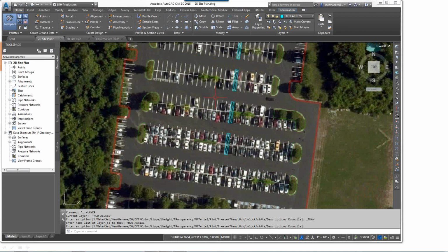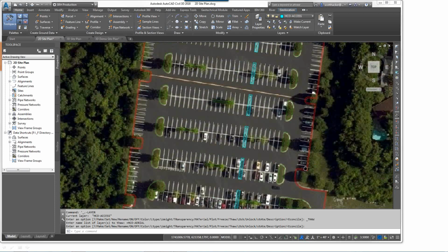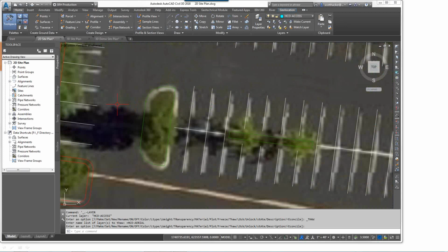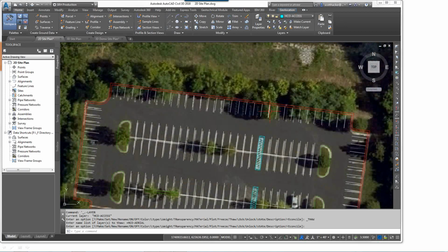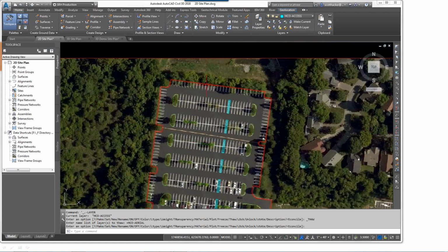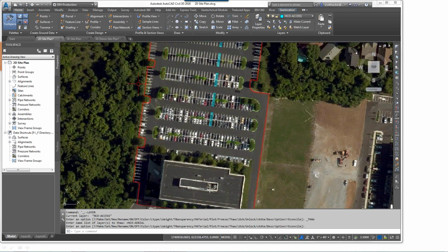So what I've basically done is disregard the aerial as far as layout and whatnot, because you'll have a completely blank canvas. I pretty much just tried to follow what the parking was, line up my stripes as 9-foot stripes, parking spaces, 2-foot vertical curb, etc. I'm really just going to show you the layout for parking and getting that into InfraWorks and how we can make that look like something that visually and 3D wise makes more sense to us.